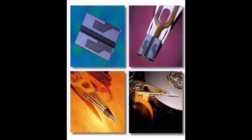When we come to the present applications, the basic one is magnetic recording heads. The magnetic heads which are used in solid drives are used to read and write data into the hard disk. ALD aluminum oxide has been used in gap layers since 2000. A thin conformal insulating film is needed, and ALD saved the life of the whole technology.